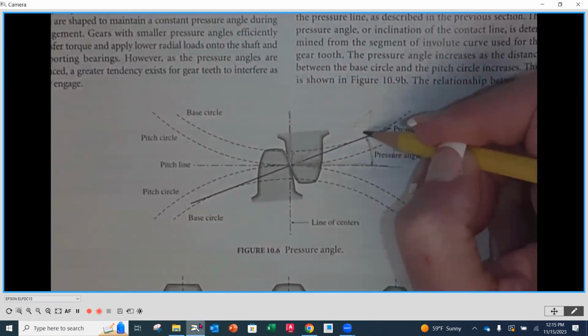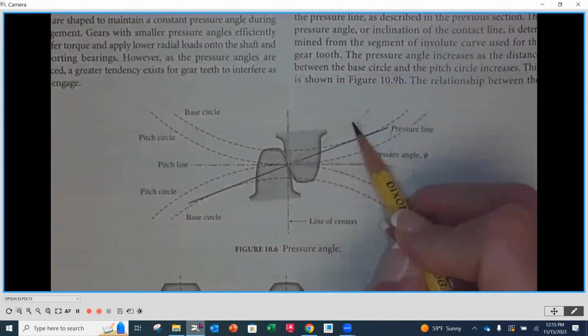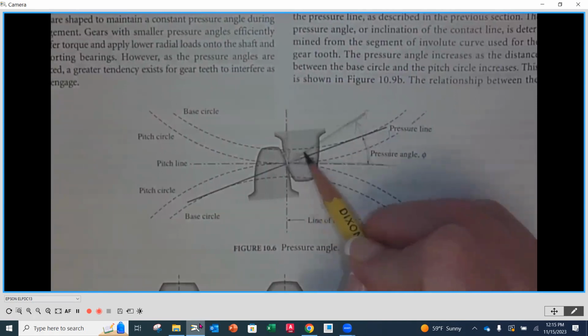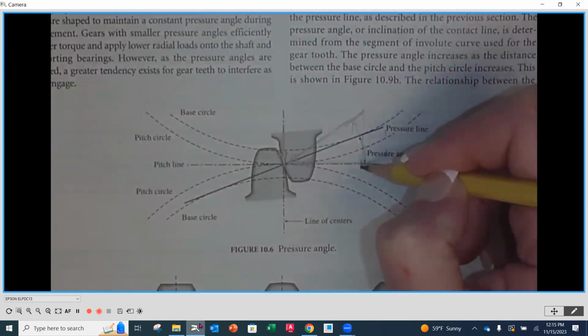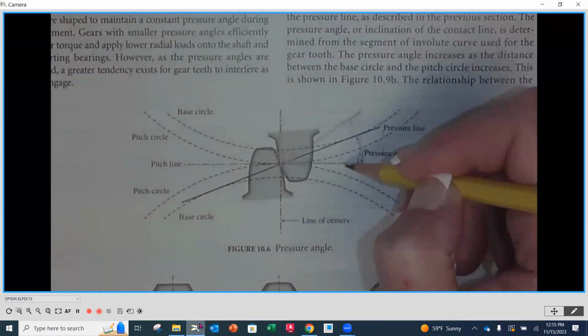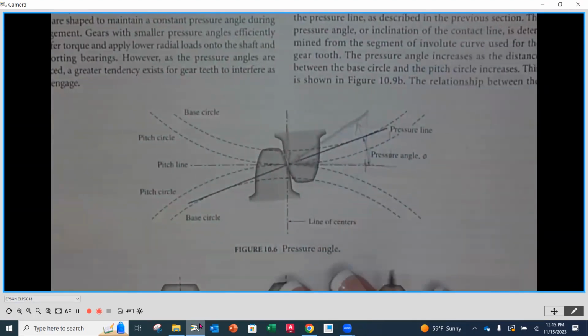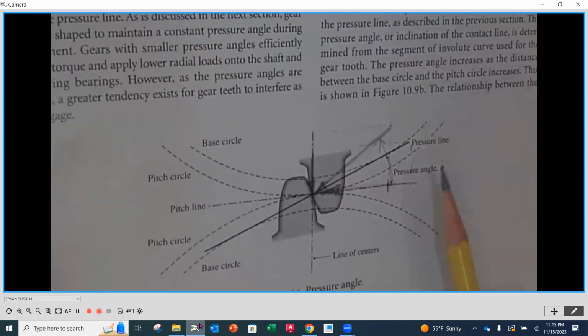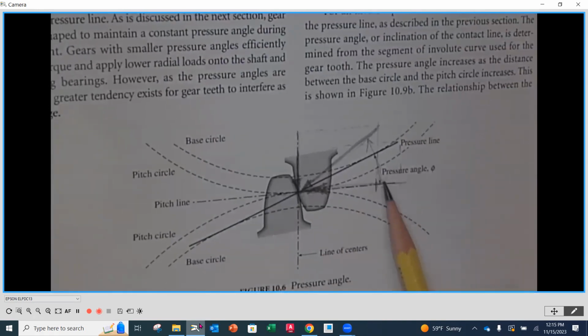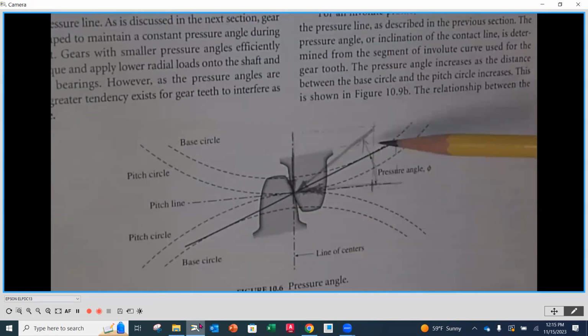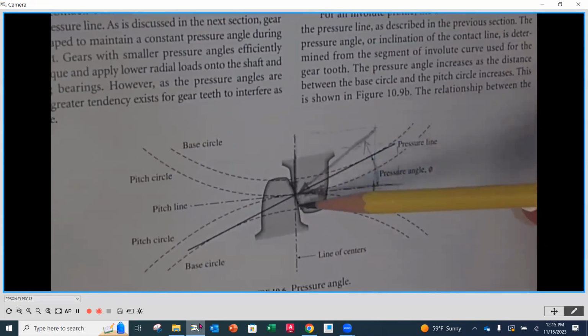So if I increase this angle by 5 degrees, for instance, and I have my resultant coming in at a steeper angle, but it's the same number, my tangential is going to shorten up. Do you see that? Maybe I've got to do this so you guys can see it. My tangential is this force going in, and it's going to shorten up. But then my radial is going to come over, and it's going to get longer than at 20.